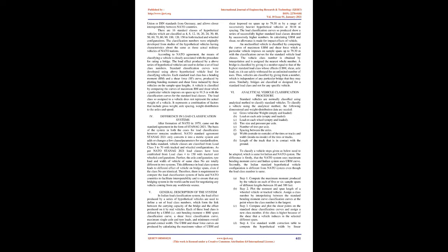A vehicle is classified by comparing the curves of maximum BM and shear which a particular vehicle imposes on spans up to 91.5 m with the classification curves for the standard load classes. The load class so assigned to a vehicle does not represent the actual weight of a vehicle. It represents a combination of factors that include gross weight, axle spacing, weight distribution to the axles and speed.